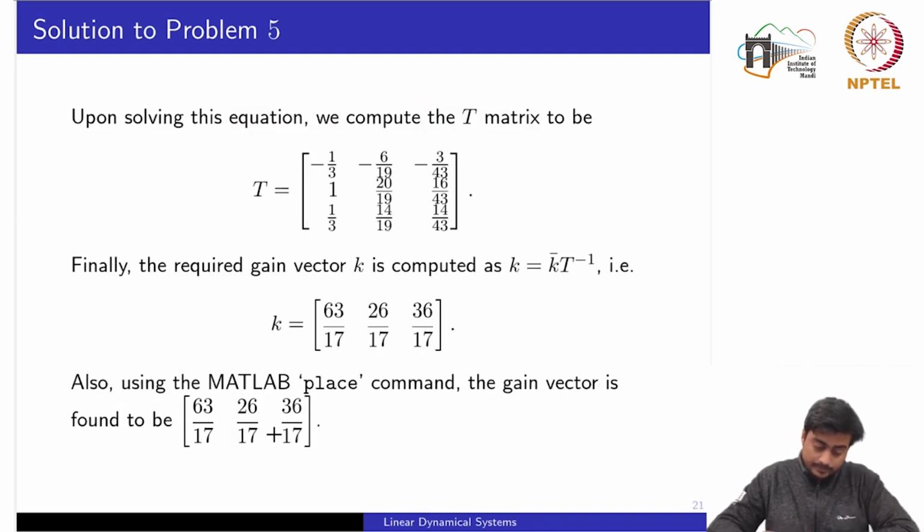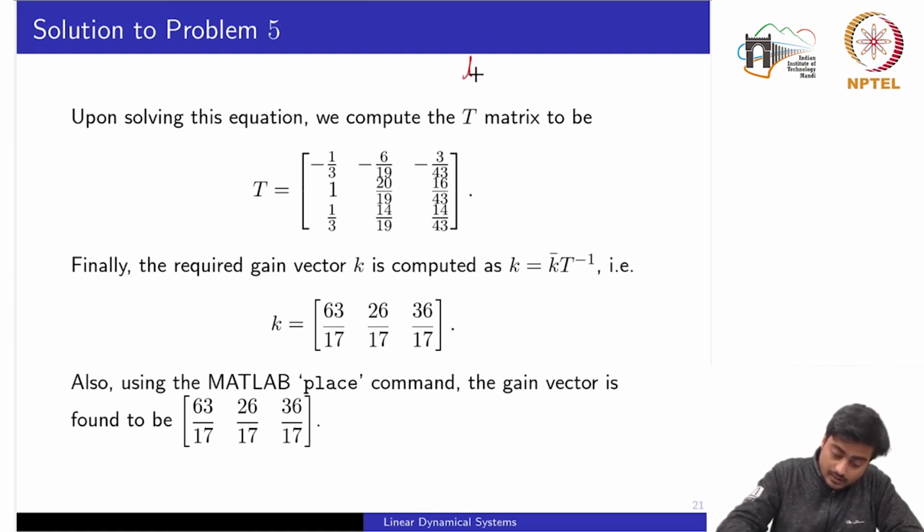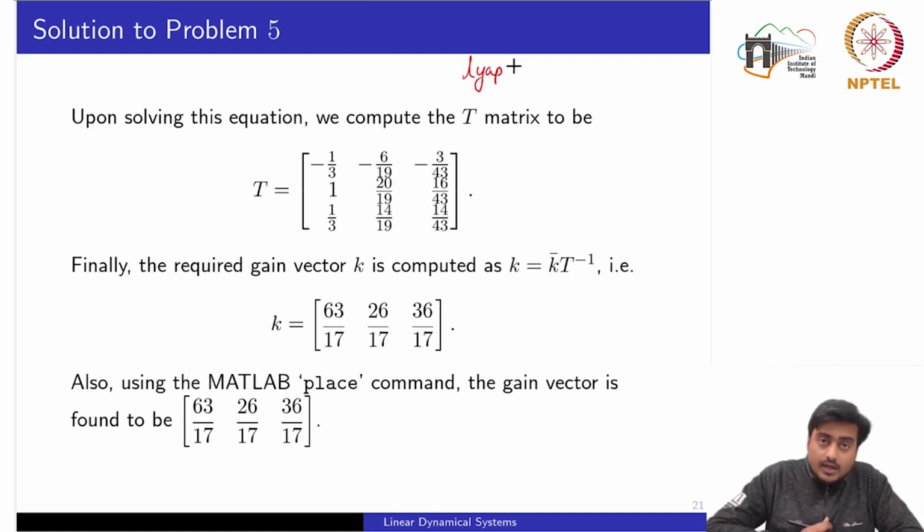You can use the MATLAB function lyap to compute this matrix T. We also commented during the lecture that this T matrix should be non-singular. Otherwise you cannot compute the state feedback gain using this equation, which involves the inverse of the T matrix. So from there we compute k equal to this one.